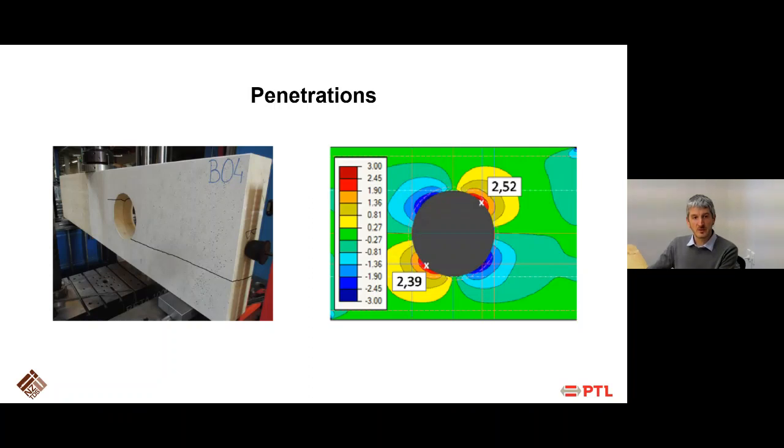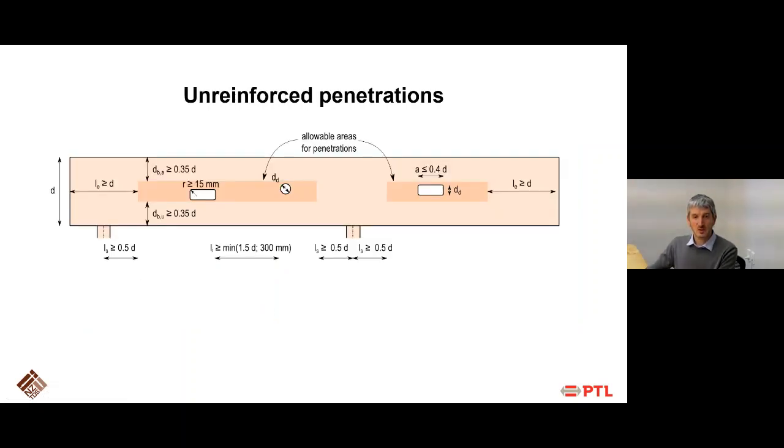Similar as before, if you cut out a piece of timber in the middle of your beam, you have not only shear forces, but also bending forces trying to go around your opening. And they create both, again, shear stresses and tensile perpendicular stresses. If you don't consider those, the timber might crack open as shown here on these sample specimens.